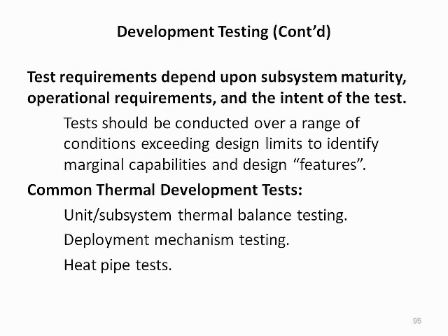Development test requirements depend upon the maturity of the subsystem and its operational requirements, as well as the intent of the test. Where practical, these tests should be conducted over a range of operating conditions that exceed design limits in order to identify marginal capabilities and design features. Common thermal development tests include unit or subsystem thermal balance testing, deployment mechanism testing, and heat pipe tests.